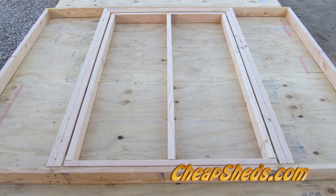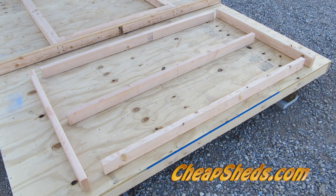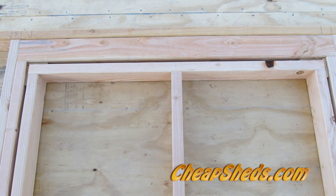Everything should fit tight. Remove the inner door frame pieces and lay them on the floor and assemble everything with screws. Verify that this assembly lays flat and is not warped in any direction. Lay this inner door frame inside the outer door frame with the spacers at the top and sides. It should fit tight and not move around.